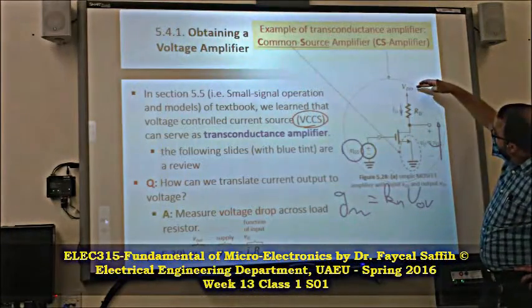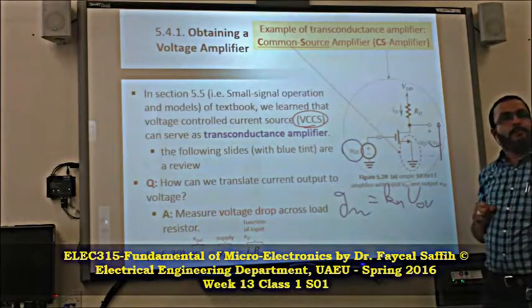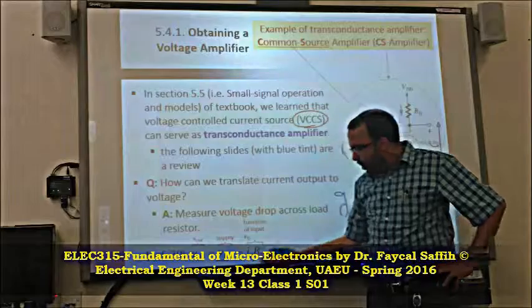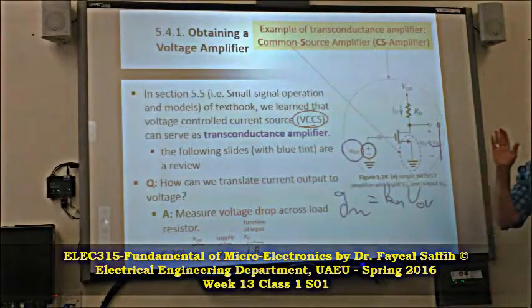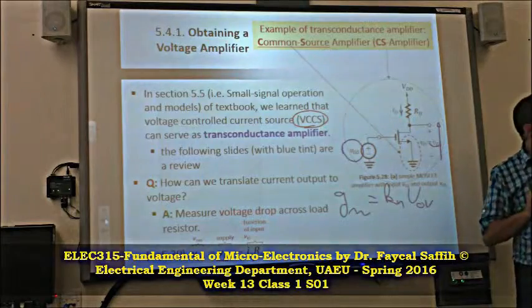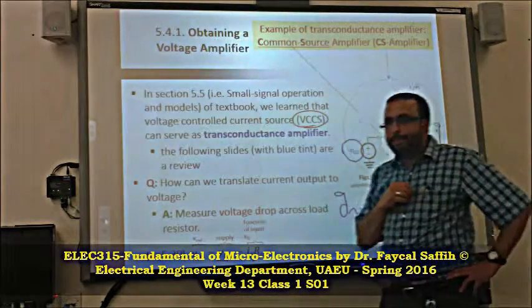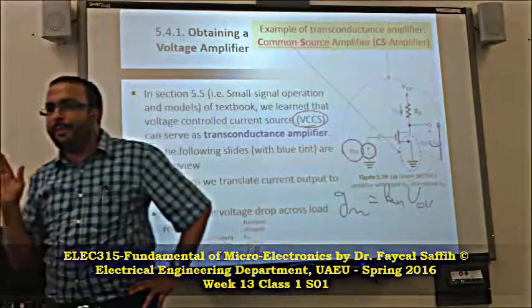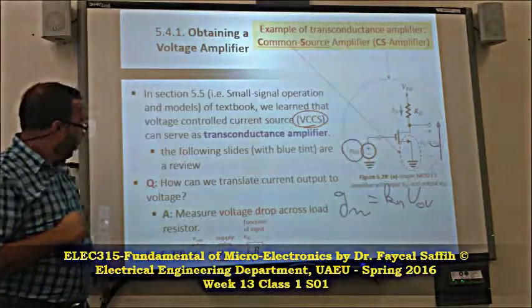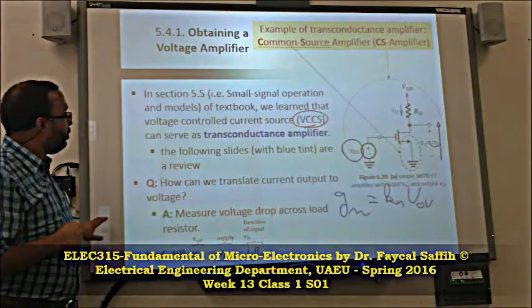This voltage is equal to VDD minus the drop, which is ID times RD. Simple, the current times RD. Nothing really, we are not making it a big deal.